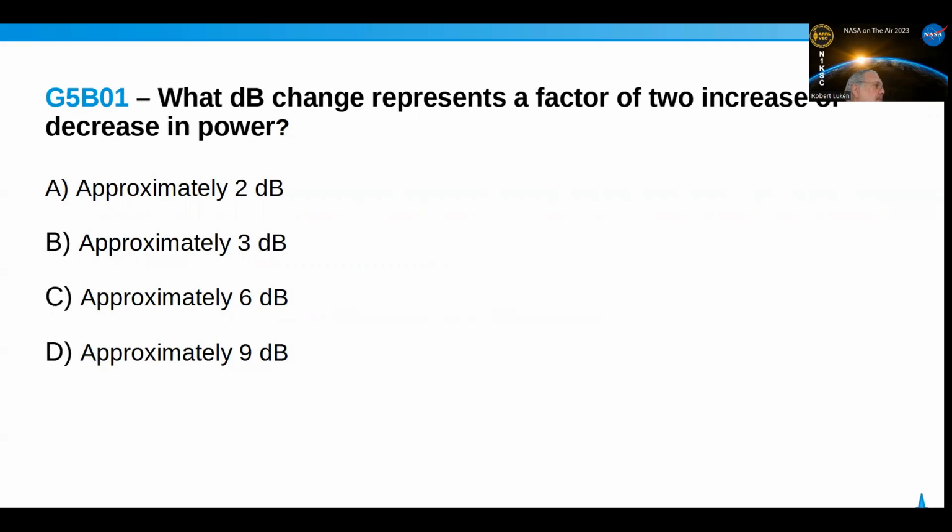If I go up to 80 watts, I've effectively doubled it again. And then if I turn up to 320, again, I'm basically going to 1300 watts around there. So from QRP to the legal limit is only a few S units. And an S unit is approximately minus 6 dB.